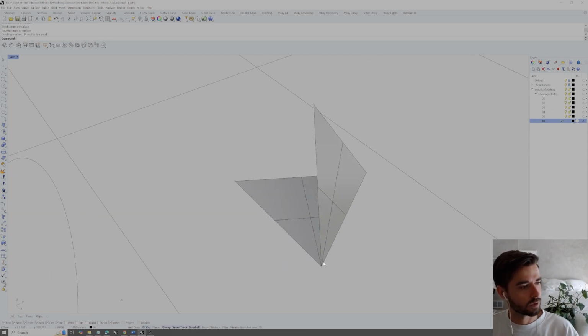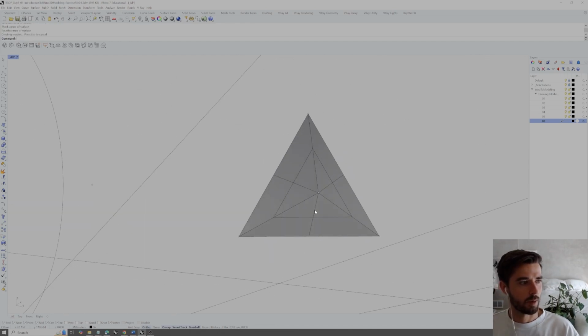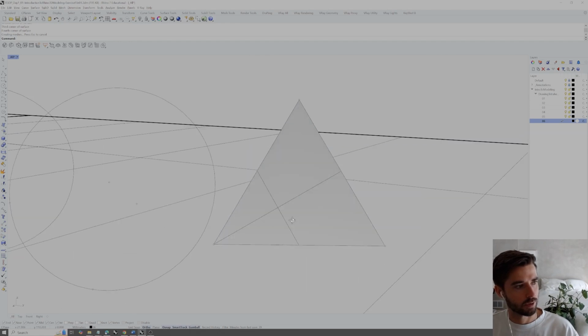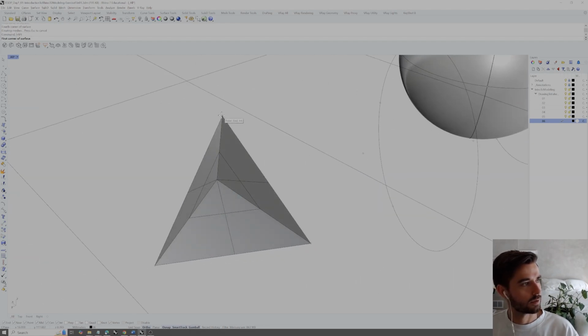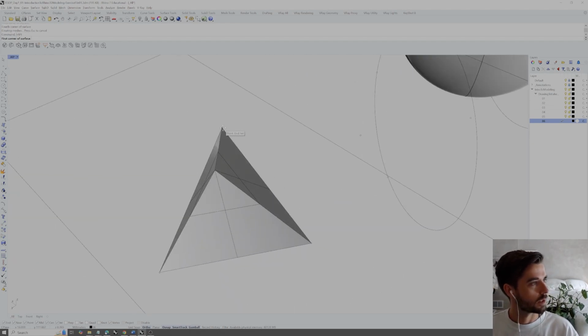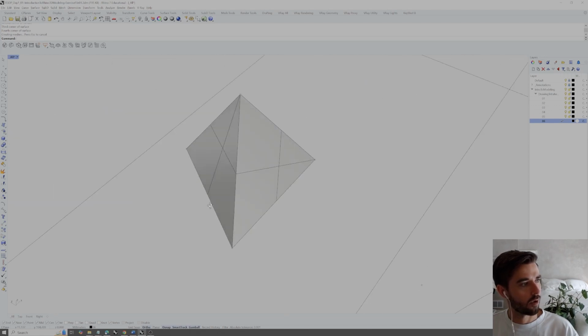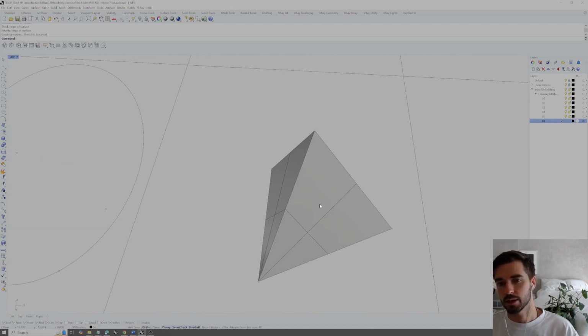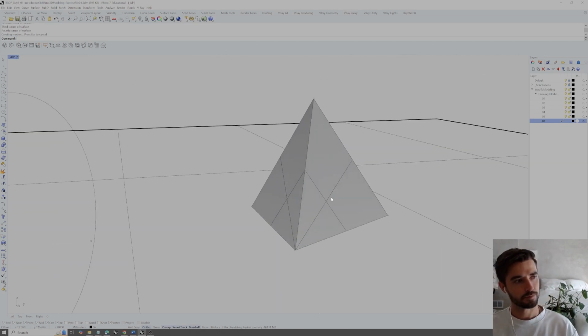And now again, we'll do point 1, now 4, 3, and then back there. So we can even see that we're starting to align with the specific ordering of those points. We're aligning our ISO curves there. And now here we can do, let's do from here point 4, and then just go around to close off this geometry. Now all of our ISO curves are totally inline oriented to match each other.